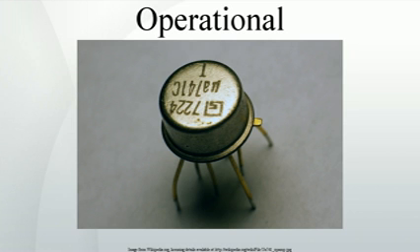Classification. Op-amps may be classified by their construction. Discrete, built from individual transistors or tubes valves. IC, fabricated in an integrated circuit, most common. Hybrid. IC op-amps may be classified in many ways, including military, industrial, or commercial grade. For example, the LM301 is the commercial grade version of the LM101, the LM201 is the industrial version. This may define operating temperature ranges and other environmental or quality factors.